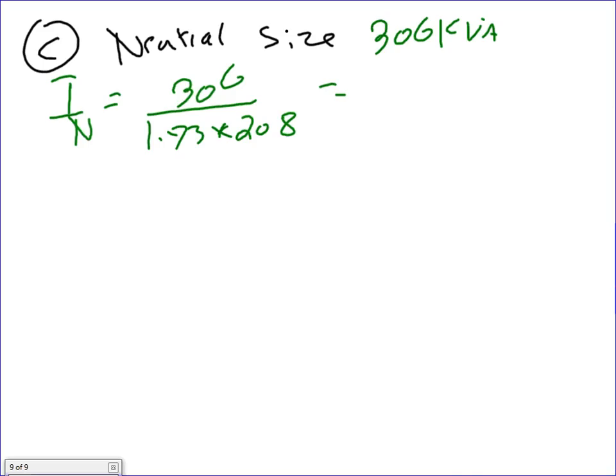Say, why are you dividing it by three phases? Because it's going to be balanced between the three phases. If this goes in one phase, you're doomed. Yes, it's a neutral load, but it's going to be balanced by the three phases. So 306 kVA. Okay, anybody has a calculator handy?